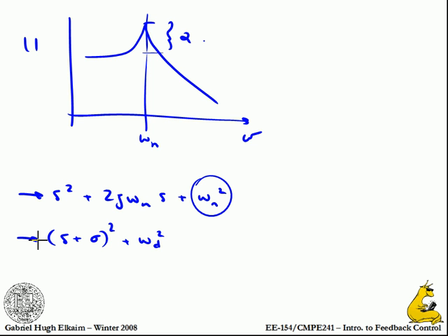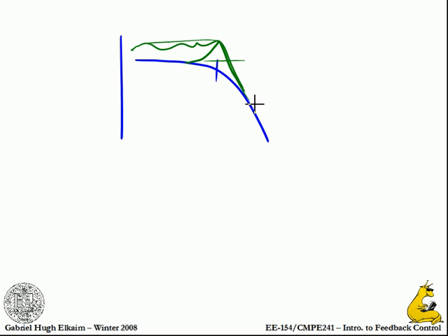Whereas if you want to see the maximum amplitude you can get on the system, the 3 dB point would be for a low pass or a high pass. There is no resonance there. The resonance you'd see is in a typical second order response, and then it's not 3 dB anymore. You can get this little peak up there, which if you're designing Chebyshev or other kinds of filters, you can actually tweak that peak to make it go up and do things like that. But no, so it doesn't.